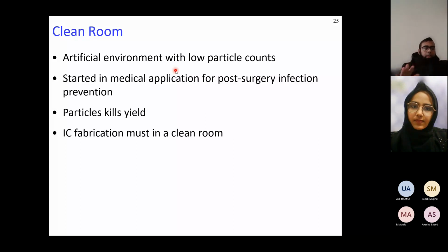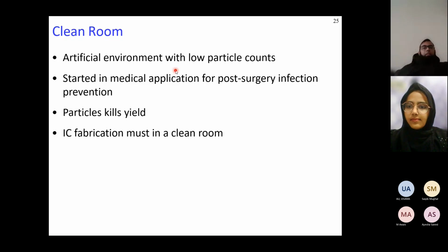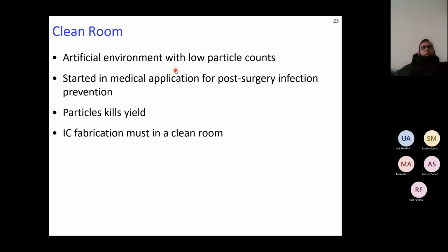Any kind of semiconductor process is done in a clean room to avoid any kind of particle contamination, like any dust particle, right? If you see in any room, a dust particle around may be 50 micron, or maybe less, say 10 micron size. But if that 10 micron particle sits on my transistor, and my transistor gate length is around 10 nanometer or 22 nanometer, it will cover so many transistors and damage my full device. So that's why we need a very clean room.